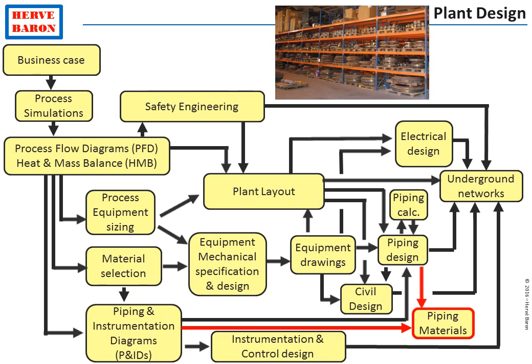Once the piping and instrumentation diagrams have been agreed between the engineer and the owner, the plant layout has been frozen, and the pipe design has progressed, it's possible to prepare the first list of required piping materials and to order the same. This is very critical, as piping is indeed what determines the duration of a project. It is on the critical path of the project.